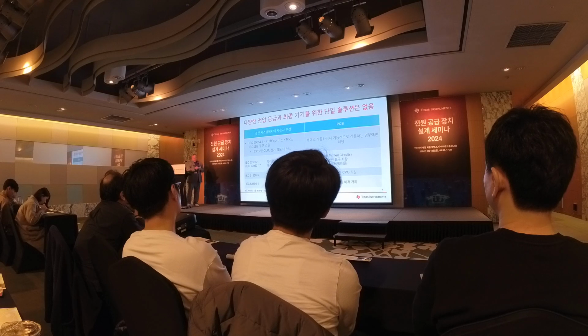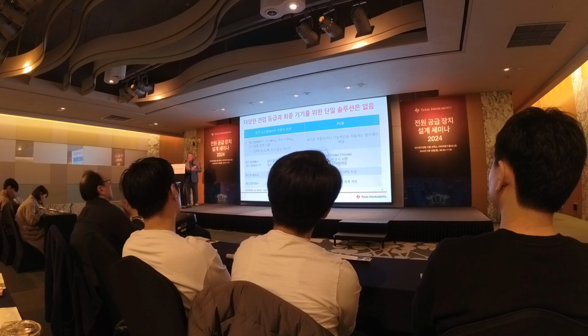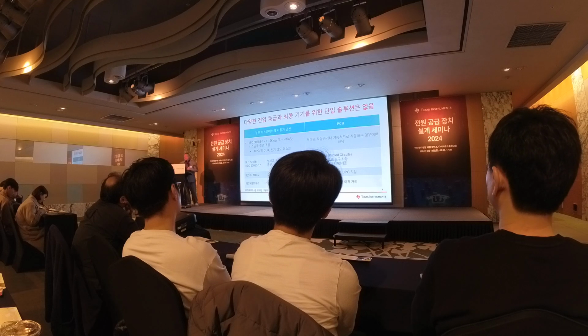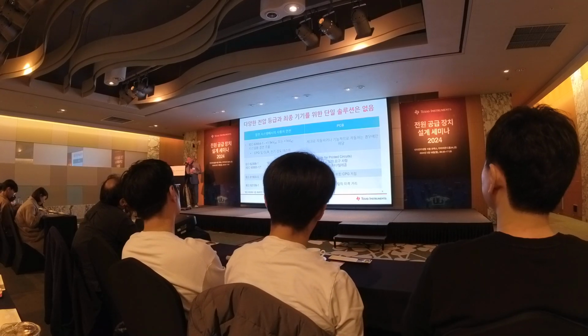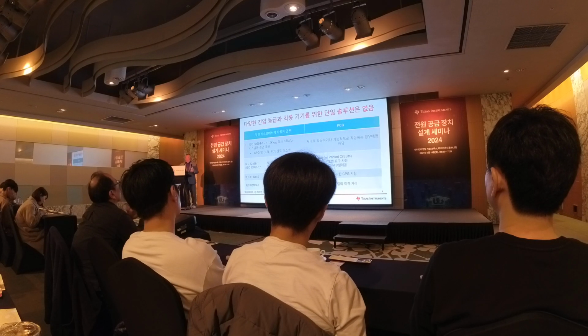The first one that's listed over here, this is based on user safety. So all of these IEC standards that we show over here for creepage and clearance are for user insulation and user safety. The second column that we listed over here is for the PCB, and these are for high voltage spacing and for proper and reliable operation of the circuit, not necessarily for safety.